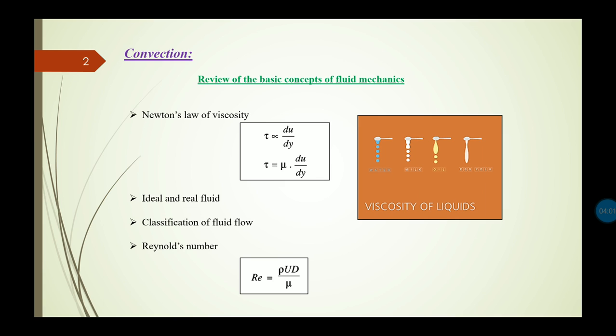But what may be some other in-depth difference between the solid and the fluid? The fundamental difference between a fluid and a solid lies in the response to a shear stress of the respective materials. For a solid, the strain is a function of the applied stress, provided that the elastic limit is not exceeded. But for a fluid, the rate of strain is proportional to the applied stress. So this is the fundamental difference between a fluid and a solid in terms of shear stress.